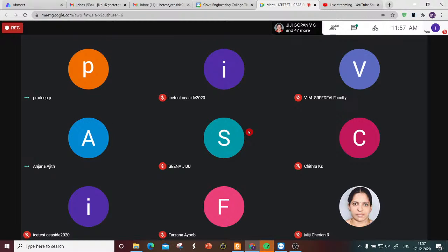So it's a manufactured aggregate, no? Yes, ma'am, sintered fly ash. Now, what about the properties of this aggregate? Is it matching with our natural sand or M sand? No, it is a coarse aggregate. Only the crushing strength is less compared to the normal aggregate.